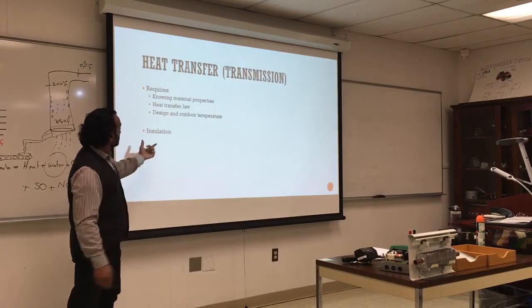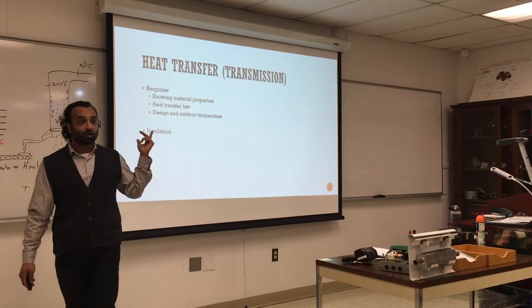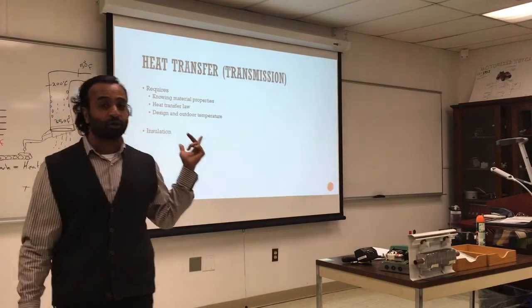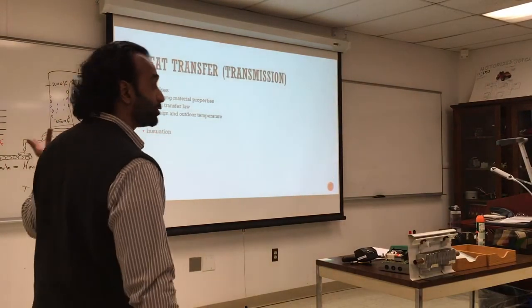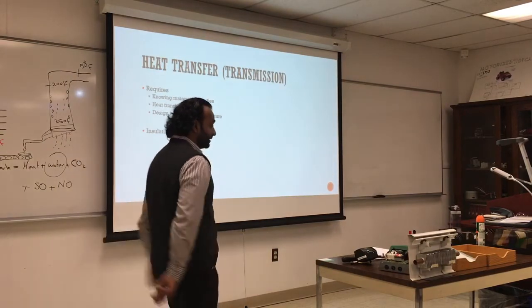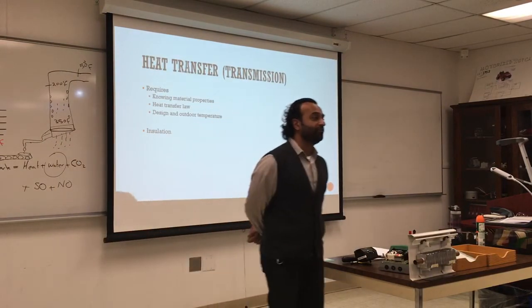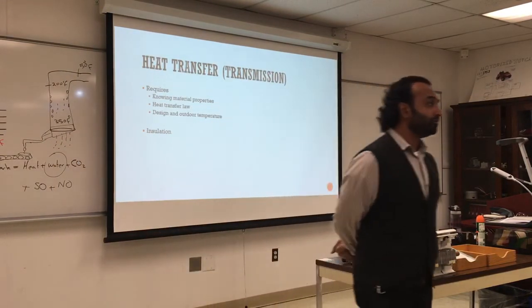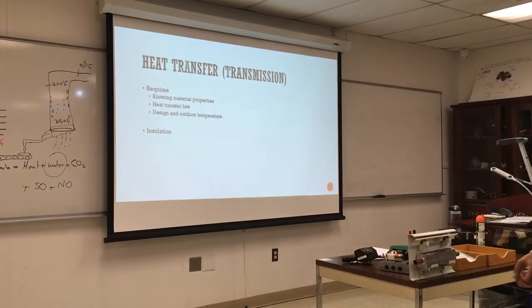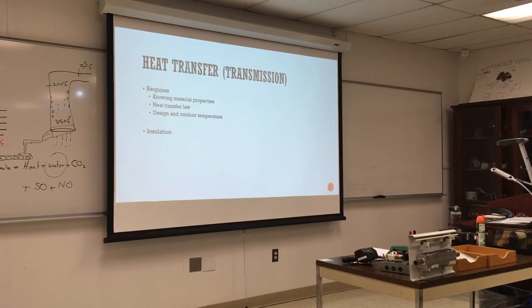Insulation. We'll talk about the insulation, and we did go over that equation in your book on how you calculate the insulation required. So we do the calculation. We find that we're losing a lot of heat from the floor or from the roof, extremely high. For example, if the room is losing around 5,000 BTU from the floor, you've got to do something about it. Or if you're losing 5,000 BTUs from the wall every hour, you've got to do something about it. You're going to install some insulation.